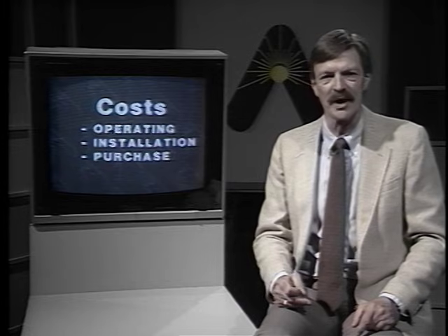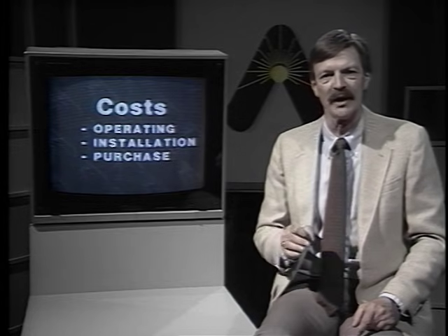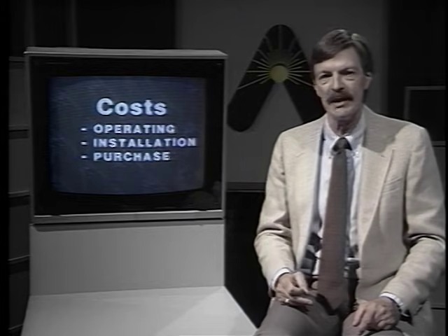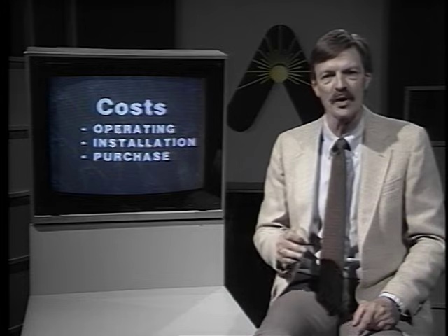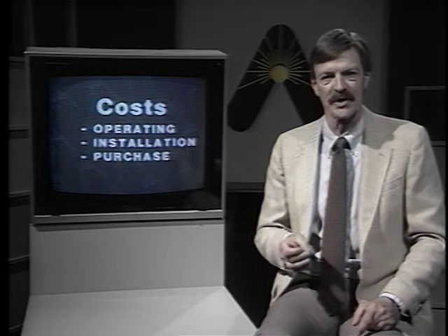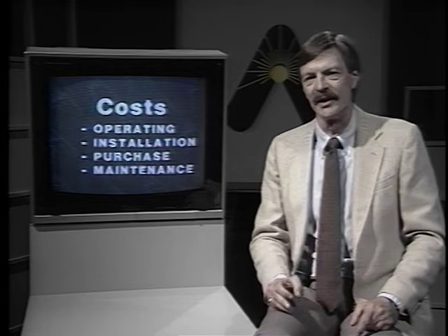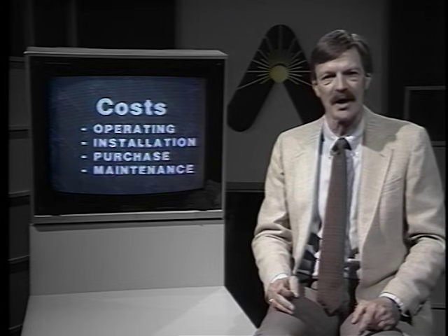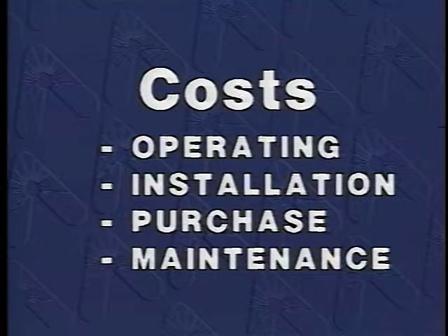Initial costs vary with the size of the units and therefore must be evaluated according to individual capacity requirements. Based on capacity alone, however, steam humidifiers have the lowest cost per unit of output, followed by water spray, evaporative pan, and wetted element systems. Added to the purchase, installation, and operating expenses are the maintenance costs.